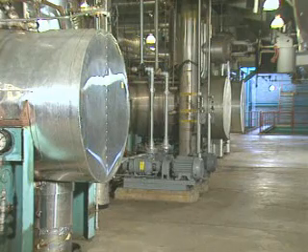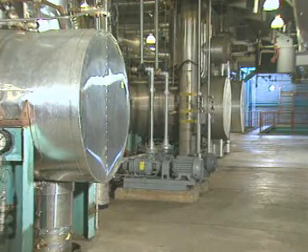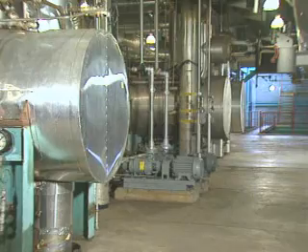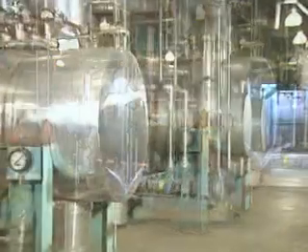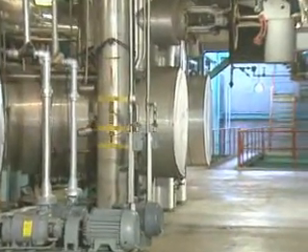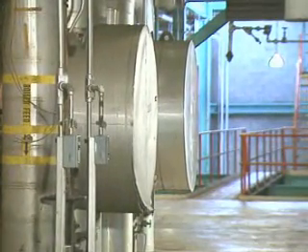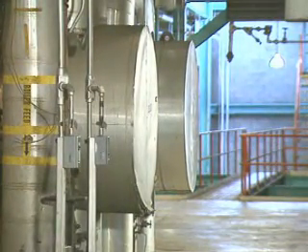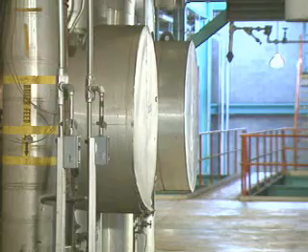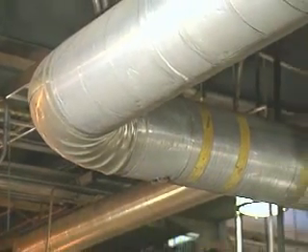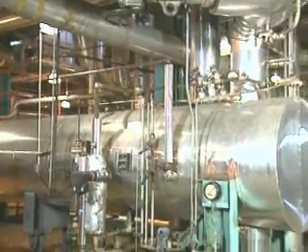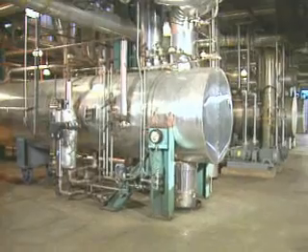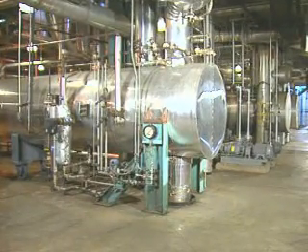In many cases, operators must determine exactly which heater in a train is not operating properly. In this example, one heater in a train of high-pressure feedwater heaters is malfunctioning. As a result, there's an increase in the temperature difference, or delta T, across the higher pressure heaters downstream from the malfunctioning one. The increased delta T causes more heat to be transferred in the downstream heaters, making up some of the difference caused by the heater that's not operating properly.